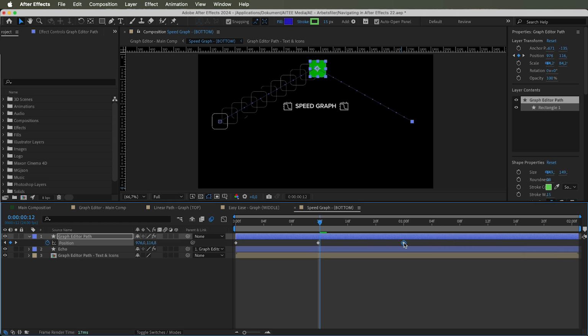Though by turning the middle keyframe into an auto Bezier keyframe, holding Ctrl or Command again while pressing it, the timing will now change and kinda smoothen out even for the left path, so as when the same keyframe is being moved.